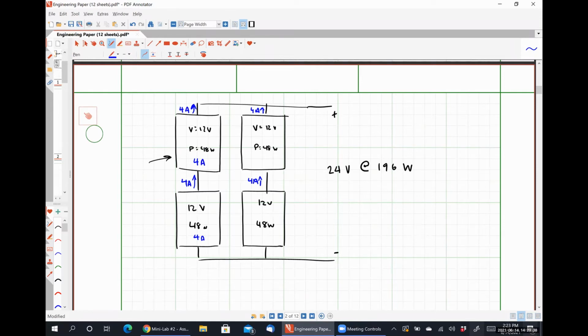My job outside of being a professor at Louisiana Tech is I work for a company called Sabre Industries out of Bossier City, Louisiana, and I work on designing battery energy storage systems. In our battery energy storage systems, we have literally hundreds of cells tied together in series to create a 1500 volt battery. And then we usually have anywhere between 20 and 60 of those battery banks tied together in parallel to output as much as 4,000 amps of current on purpose.